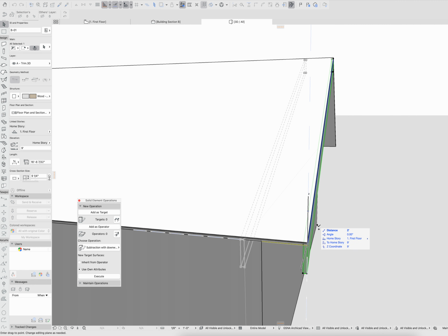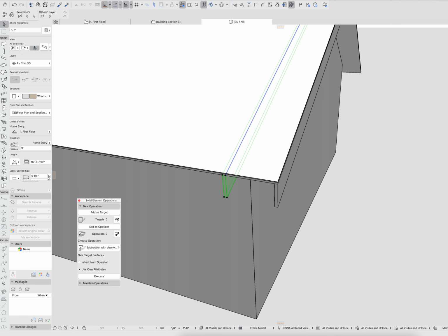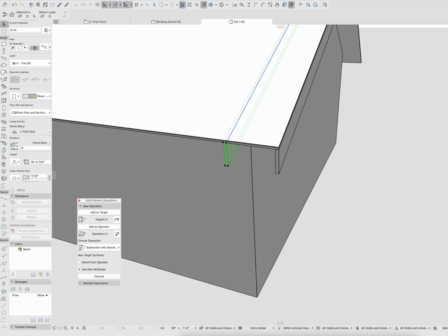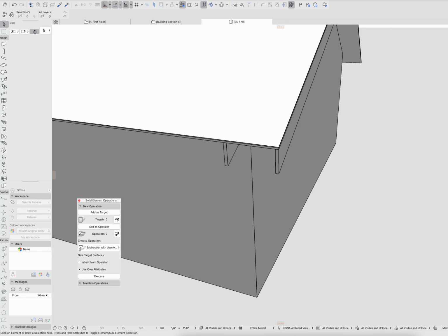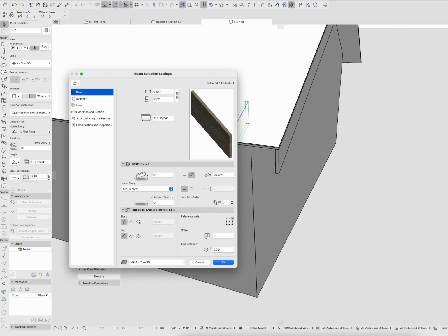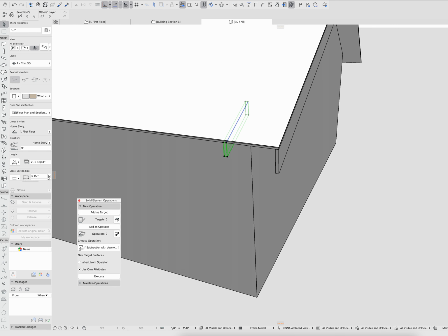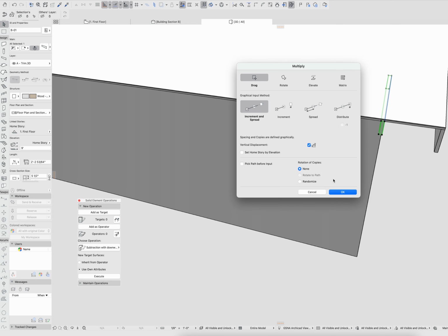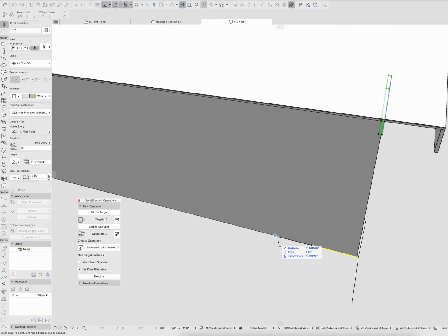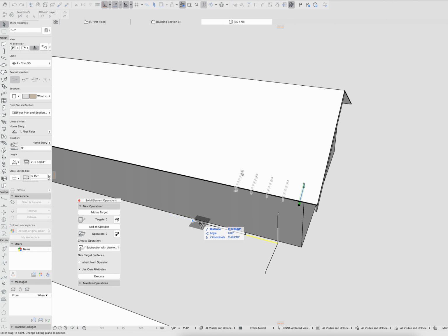Okay, and then we'll copy this over, just dragging a copy of it to the face of sheathing here. And then I'm going to take my split command again. I'm using shortcuts for that, but it's just under edit, reshape, and split, or on my toolbar, it's up here on that little axe symbol. Then I could take this guy and make this, if we've got 5.5 inch rafter tails, for example, use the multiply command to say that these rafter tails are spread 2 feet on center, or whatever the rafter spacing is, and then just copy those through, whatever spacing they're at.